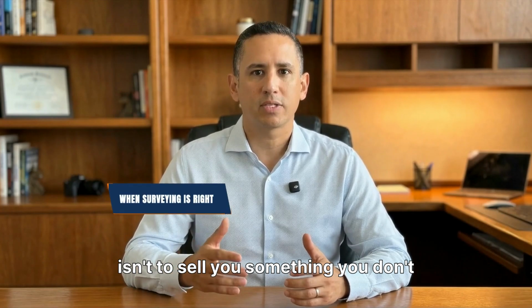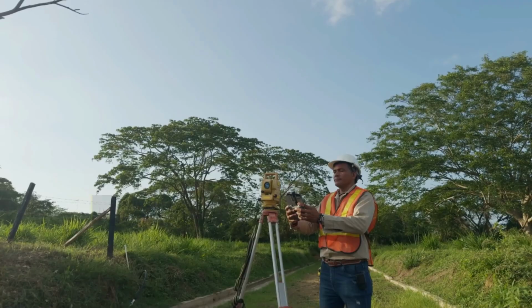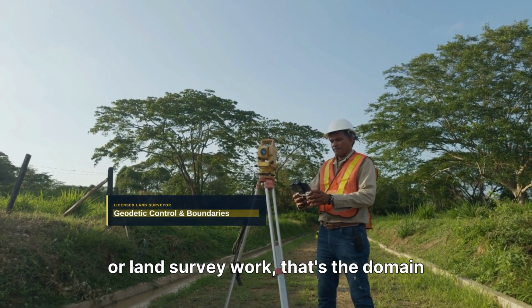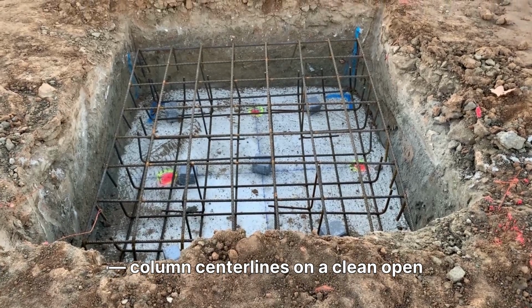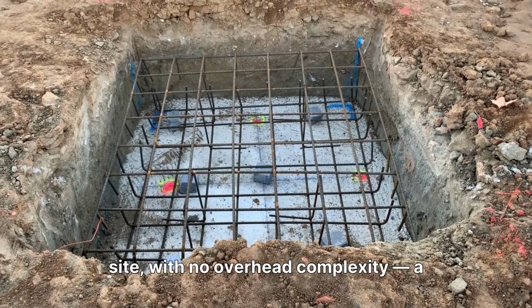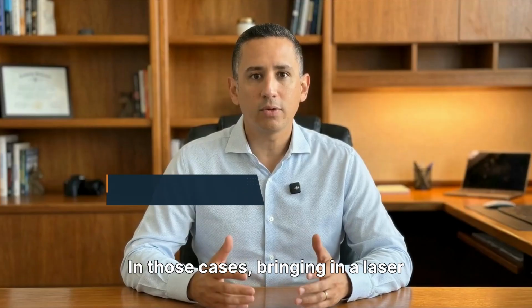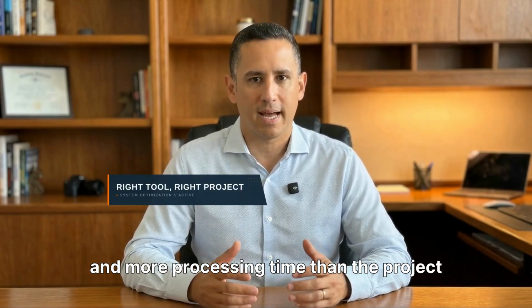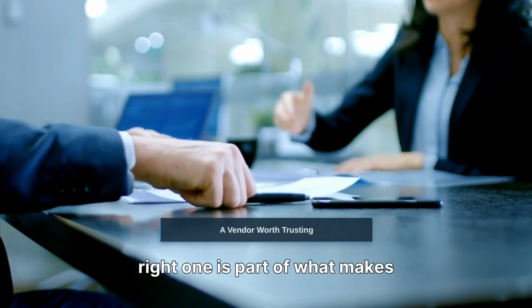Now, in the interest of being straight with you, because our job isn't to sell you something you don't need, there are situations where traditional surveying is the right tool. If you need geodetic control, property boundaries, or land survey work, that's the domain of a licensed surveyor. Full stop. And if your scope is genuinely narrow, column center lines on a clean, open site with no overhead complexity, a conventional survey may cover it at a lower cost. In those cases, bringing in a laser scan would mean more data, more cost, and more processing time than the project actually calls for.